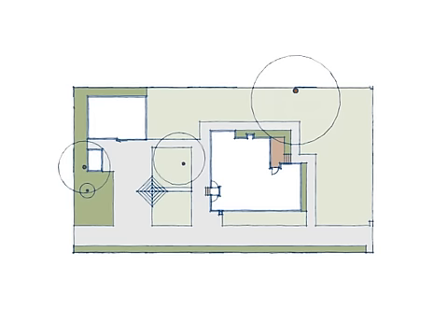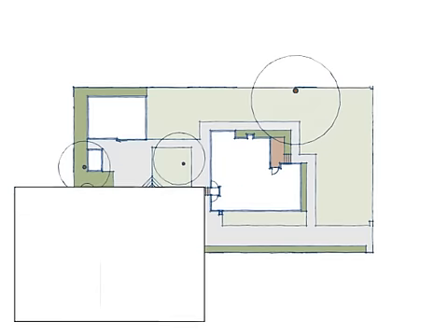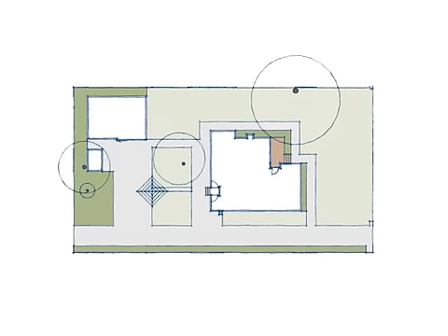Here is a section as if we were looking down at it from a helicopter, and here is our piece of paper. If we drew everything on the section at full scale on our paper, something that measured 100 millimeters on the section would be drawn as a 100 millimeter long line on the paper. This is a scale of 1:1, or full scale. As you can probably imagine, this would take a lot of paper to draw the whole section.